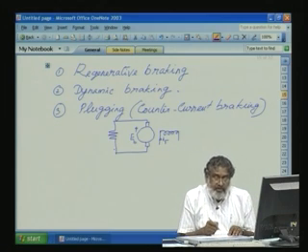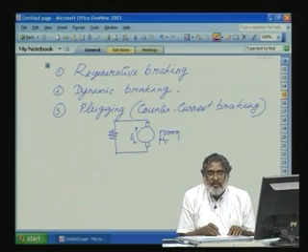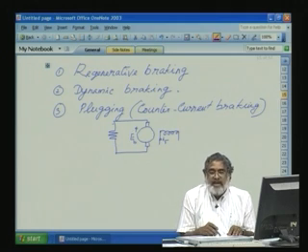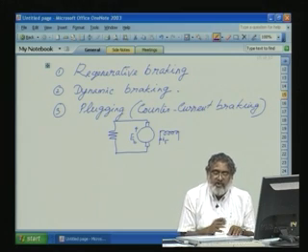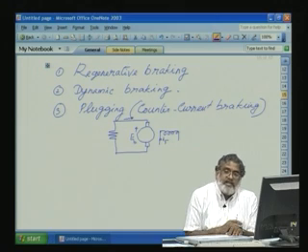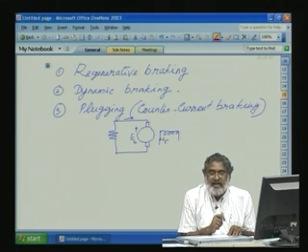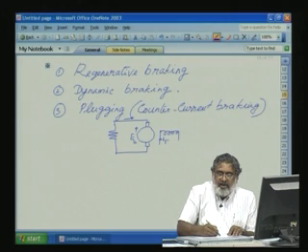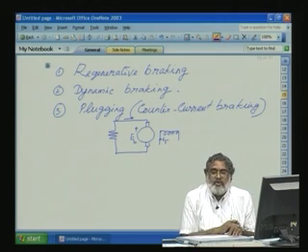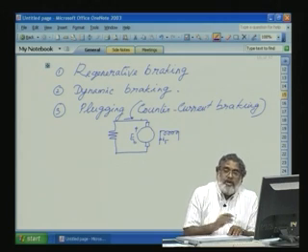So, here we are going to give a resistance. Previously we had a voltage source here and the machine was running. Now, we want to reduce the speed or stop the machine. We cannot immediately remove the power supply, because previously there was a current flowing in this direction, and current cannot change instantaneously. So, we slowly reduce V, such that when V becomes less than EB, the current flowing from the source to the load comes to 0.